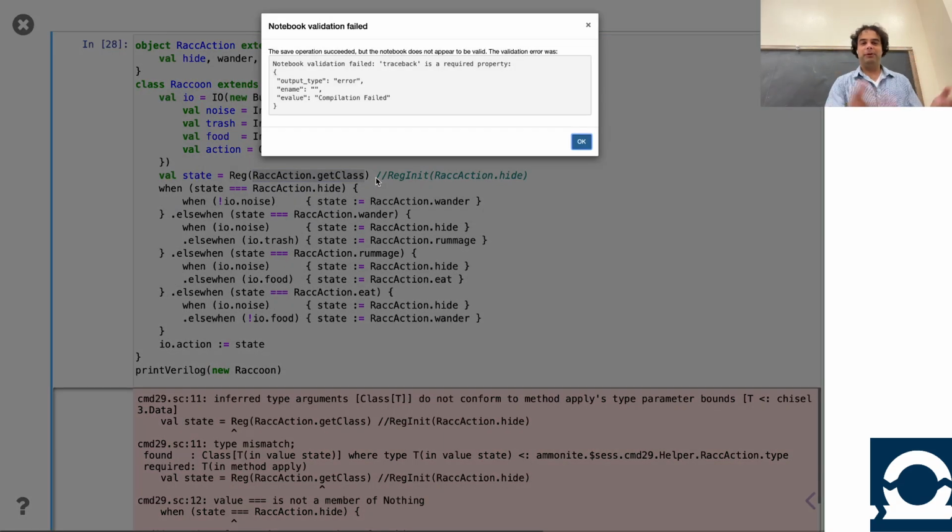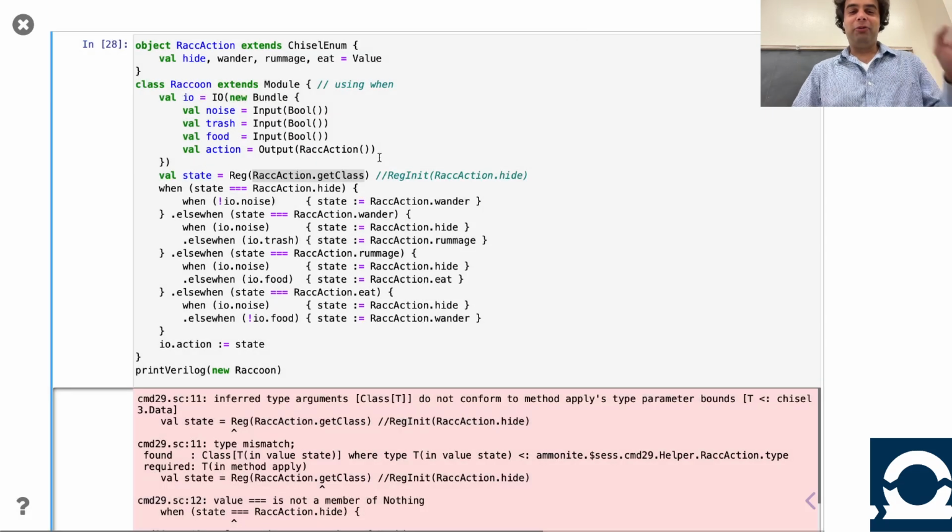So what could happen? Oh, we even wrote a notebook. Okay, so the notebook itself broke, but in addition to that, what should happen? Well, independent of Chisel versus Verilog, if you don't set the value of a register, its value is unknown. The value it has could be totally arbitrary. So if we don't know its initial value, which of these clauses applies to it is a little bit dicey because there's no initial value. You can imagine that with some really clever theory, maybe you have some very complicated set of logic such that even if the initial value is unknown, somehow it converges to some known state. That could happen. But in general, it's good practice to have registers get into known states.